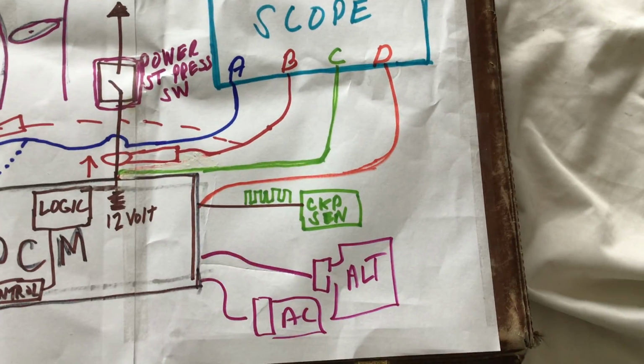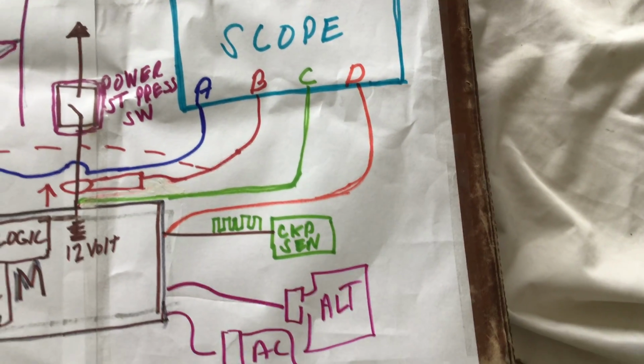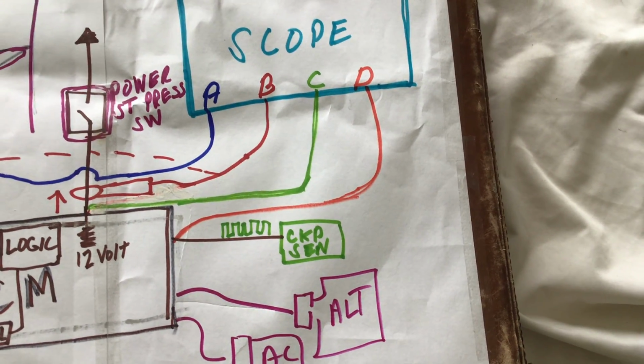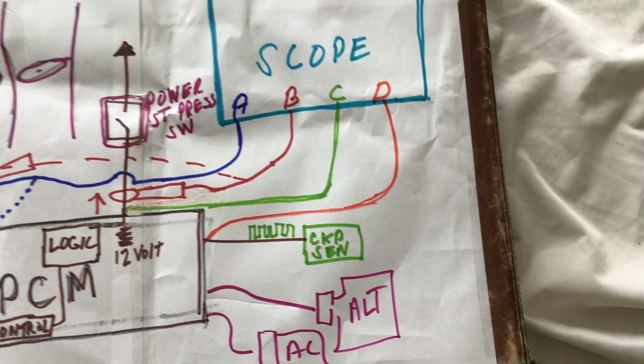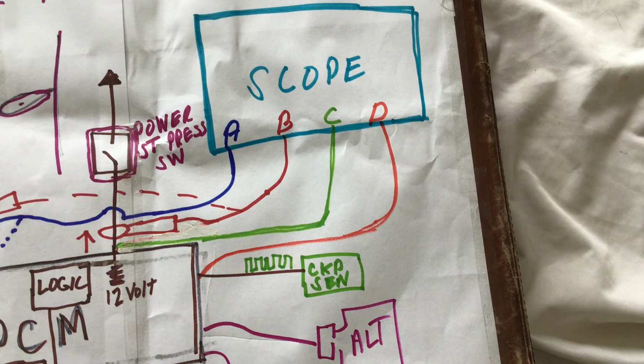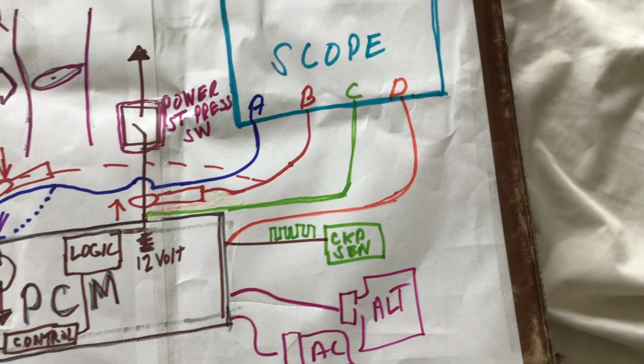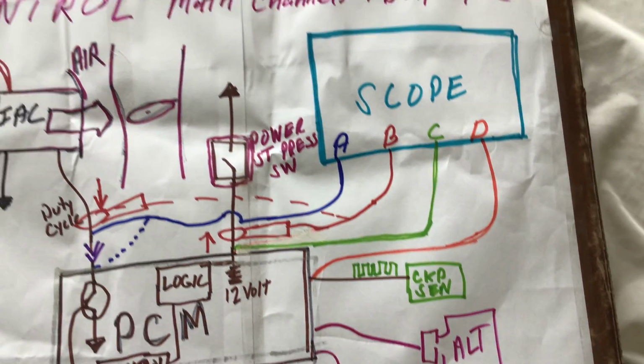We're also going to look at crank speed. That is the orange channel we'll see on the scope. Because crank speed is a good validator, it's kind of that RPM change, I will make math channels. I'll make a frequency math channel to see our RPM change, and you'll see that. So we've got 4 channels there.